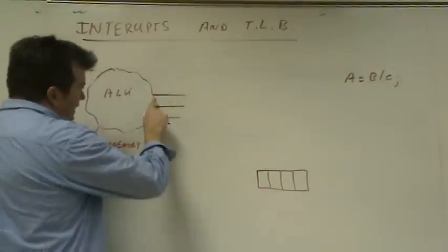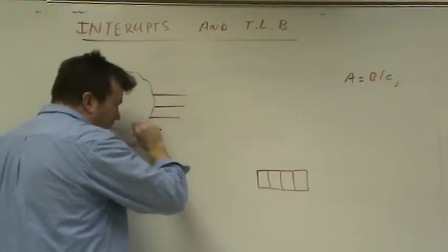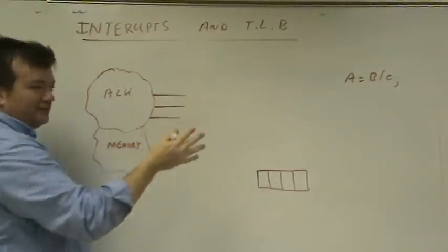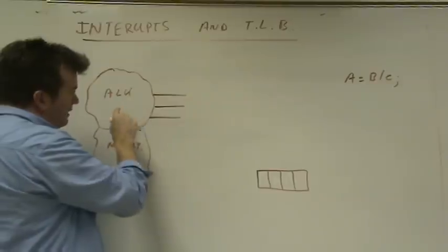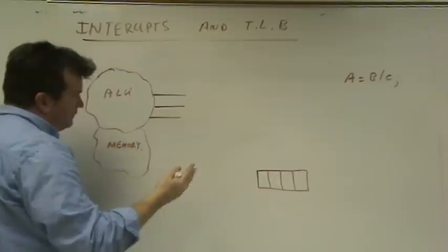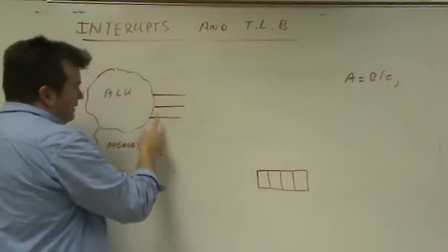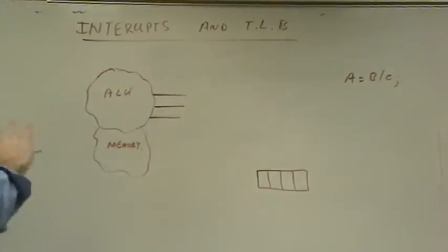So we could have, out of our hardware, different wires could come out, and that wire will turn on if the hardware detects this issue. So we'd have to wire up the ALU to say, if 2 numbers are added together and the result can't fit in the result register, turn this line on. If someone's trying to divide by 0, turn this line on, right? So we're just going to turn power on whenever we detect something's wrong.